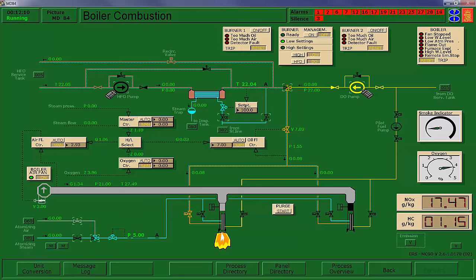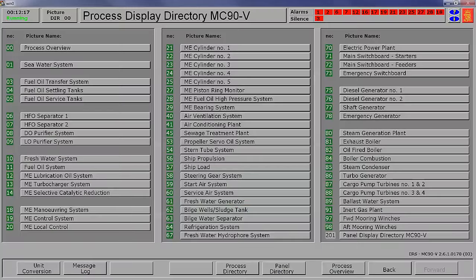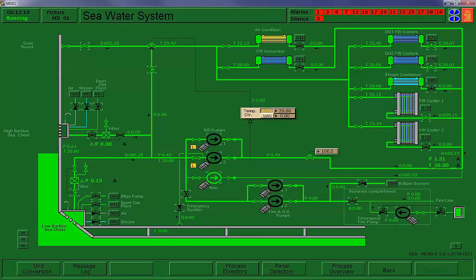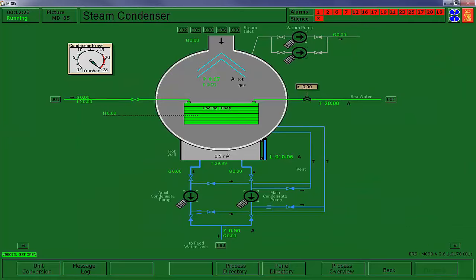Okay, so from here, I'm going to line up salt water to that main condenser. The main condenser comes off the saltwater system here. And then we're just opening it 10%, just a small amount of water. All right, and again, we shouldn't need this. If everyone's being attentive, it's a non-issue.